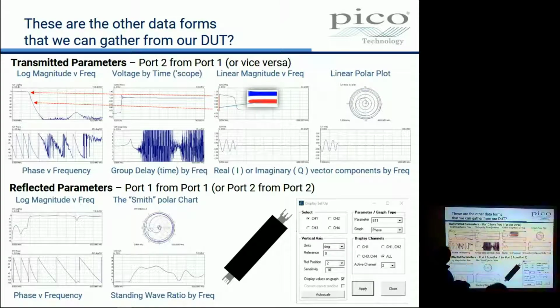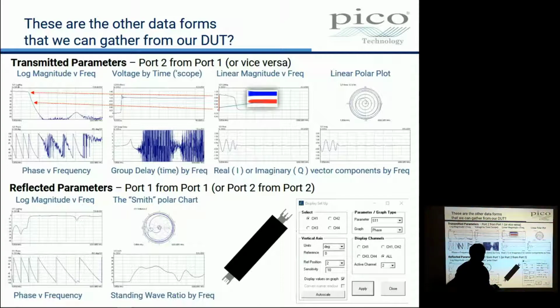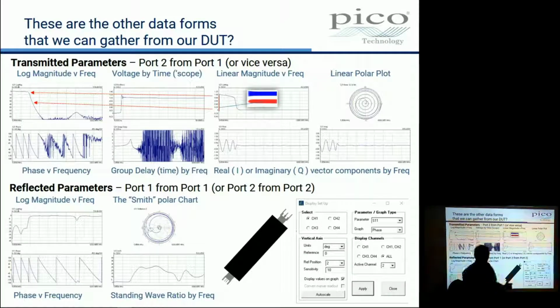So this is a low-pass filter. It is comparatively well matched low down, and the SWR reading here is 1.2 to 1, and then when it becomes mismatched, that's what we see here in an SWR plot. And this little ding here in the S11 plot is that ding there. So that SWR plot is correct. I just couldn't get my head around it for some reason the other day.